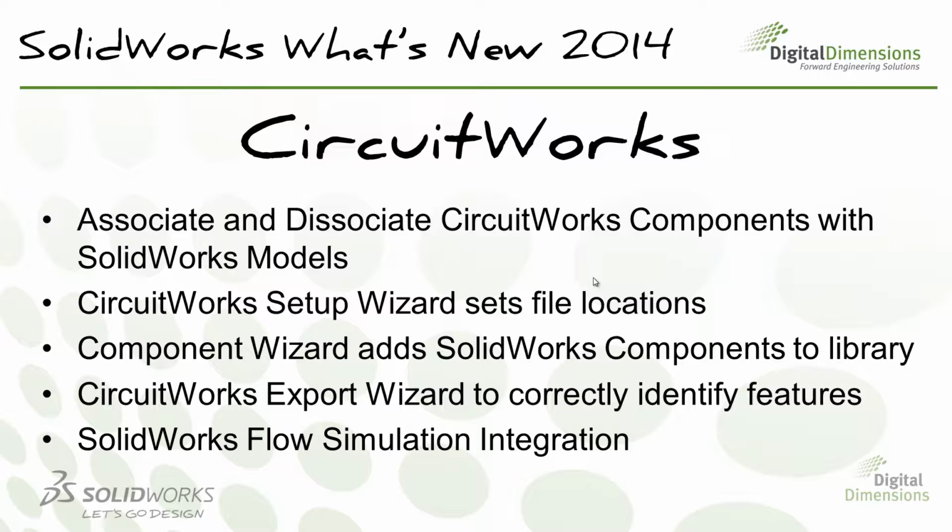Next, I'll go over the CircuitWorks Export Wizard, which is a way to bring in boards and components back into CircuitWorks so you can actually send that back over to the ECAD group. And it'll help you to identify the different things on the components that are important so you don't have to know all the syntax of how to import that in. So a real big improvement on some of the interface with these wizards.